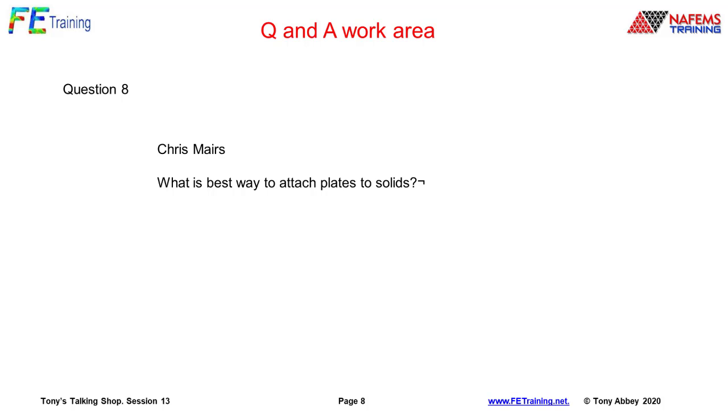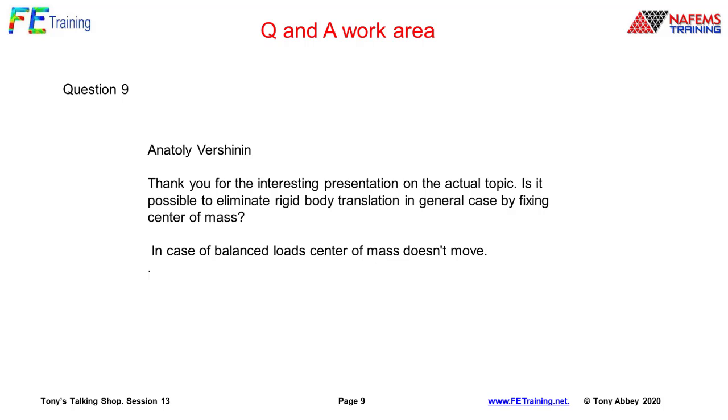There are special connectors which are basically going to use multi-point constraints. What they say is that the plate with all 6 degrees of freedom sees the solid, picks differential translations, and writes multi-point constraints between them. There are some special connectors to do that. So there's a bunch of different ways to do that.